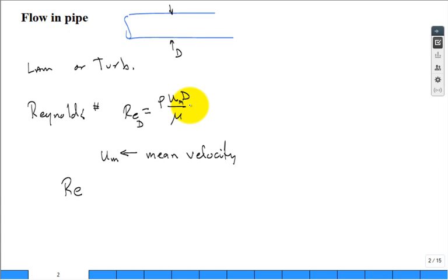So we have an interpretation of the Reynolds number. It was interpreted as the ratio of some competing forces. It would be inertial to viscous. And so when it's high, the inertial forces win, and it makes it turbulent. That's the prediction of having turbulent flow. So the Reynolds number based on diameter, for the critical transition between them for pipe flow, is 2300. Now, some books will use 2100. Some books will just say 2000. This book, I believe, says 2300. So let's stay with 2300. But it's really not that accurate. It's in this vicinity where if you're below it, we would say you're going to be laminar. If you're above it, you're going to be turbulent flow inside the pipe.